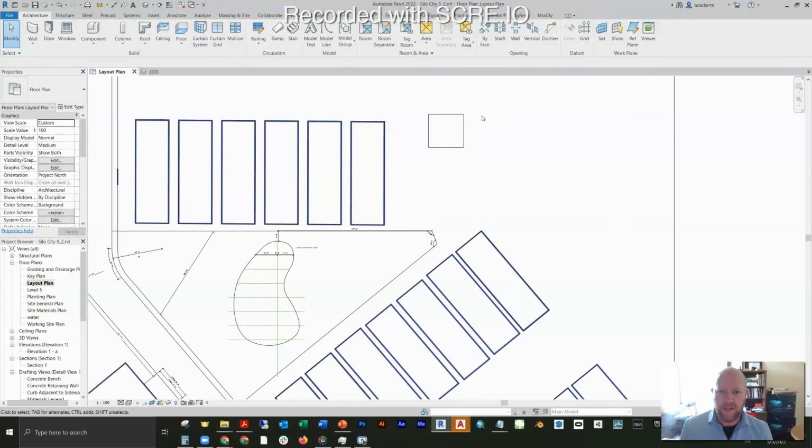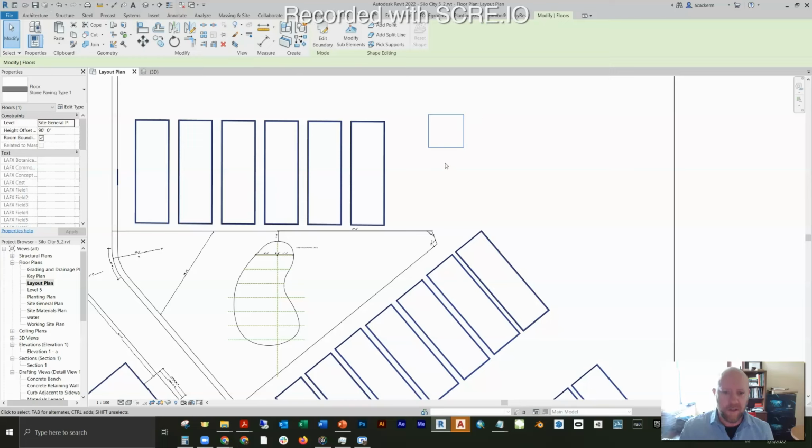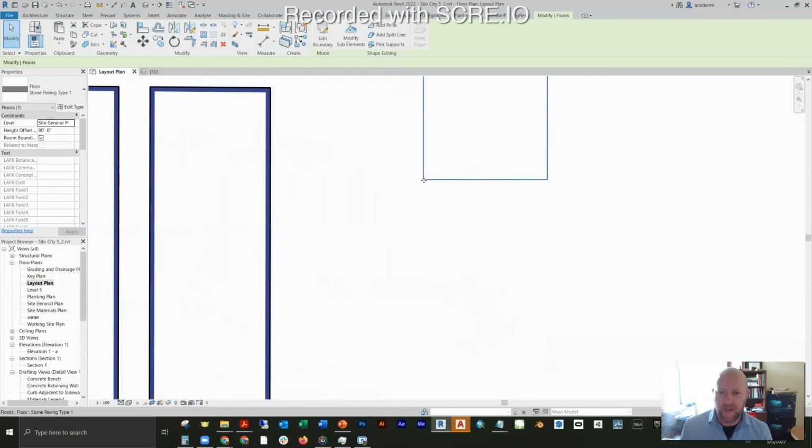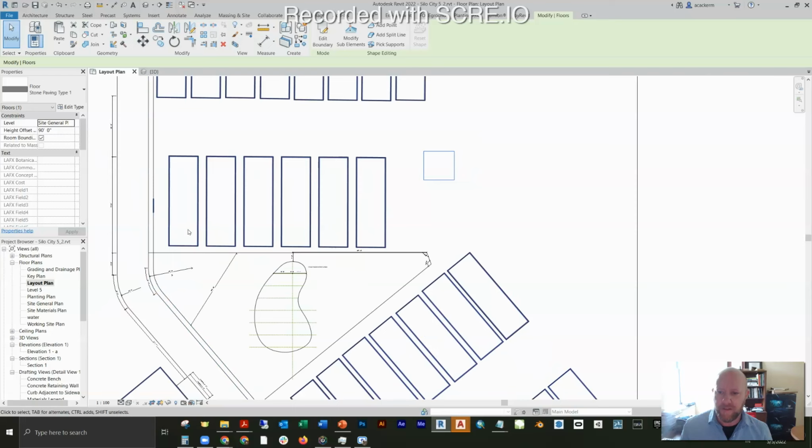Now we have floor out here, and in this scenario, it's pretty easy to dimension it off of other things like the architecture, but you might find yourself in a position where, for various reasons, there's established points on all drawings where you need to put coordinates, or we need to put a coordinate for this corner, and it may, for various reasons, be too difficult to locate with typical dimension lines. Or we may just want to mark, again, these established points in the drawing. But let's say we're going to mark right here with coordinates.